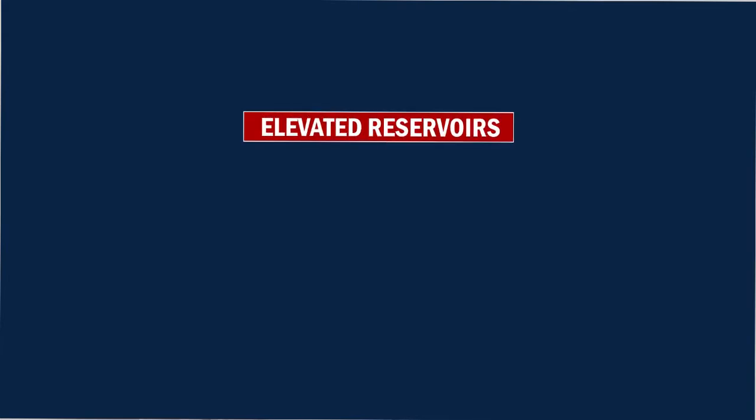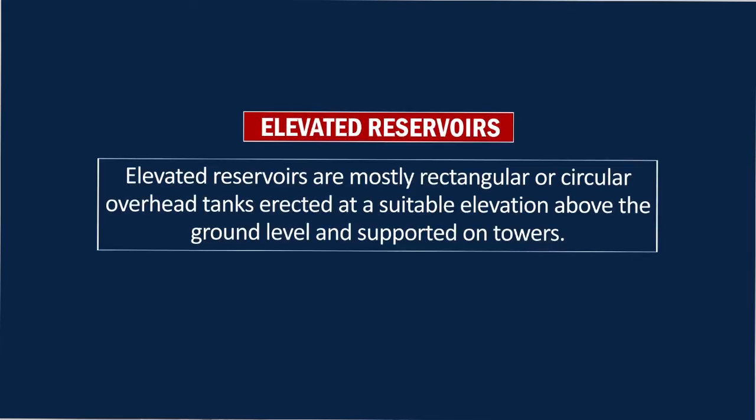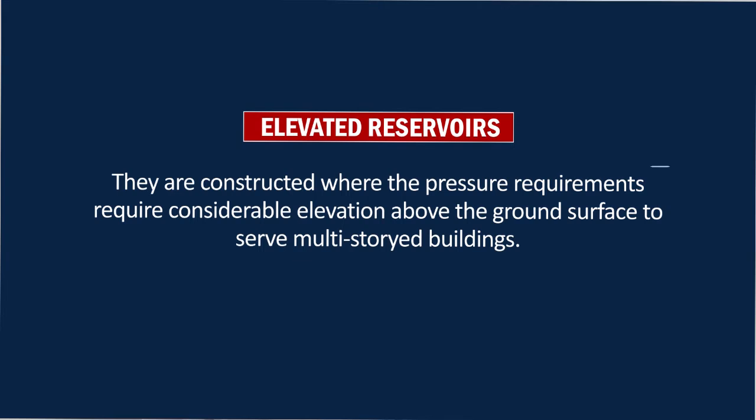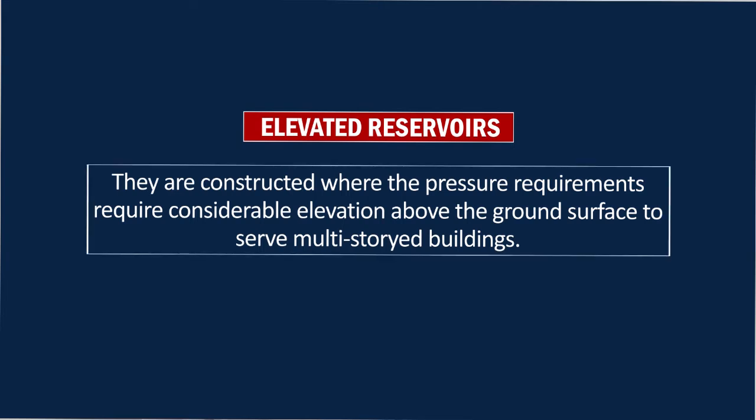Elevated reservoirs. Elevated reservoirs are mostly rectangular or circular overhead tanks erected at a suitable elevation above the ground level and supported on towers. They are constructed where the pressure requirements require considerable elevation above the ground surface to serve multi-storied buildings.